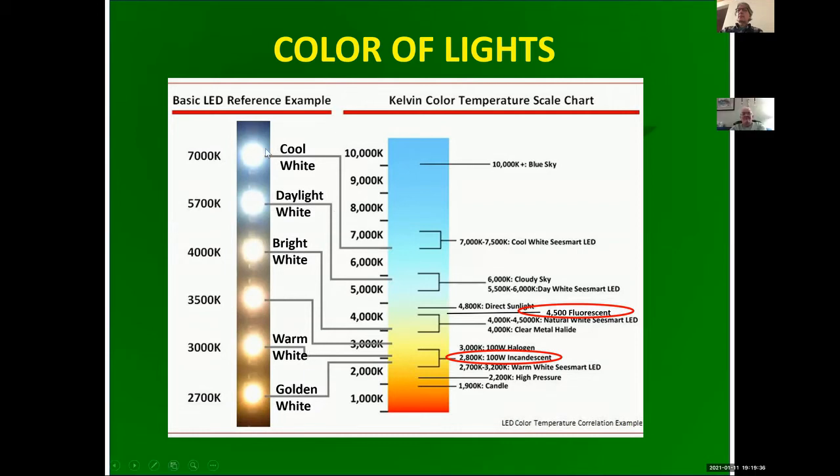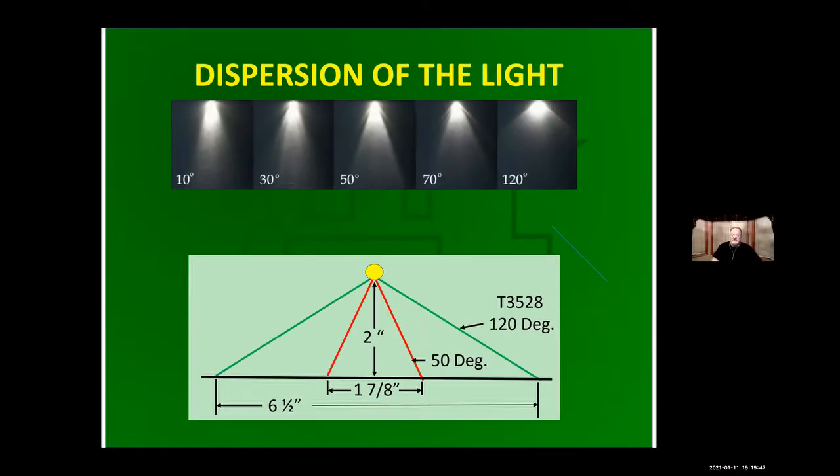I have not done that, but I'm going to do that shortly because I got some lights I think are too blue for me. Steve? Yeah, that's Tamiya. The Tamiya colors are translucent, and you can dip them in Tamiya and put an orange glow to a blue-white LED. Okay, Tamiya is the one. And you had good experience? Yeah, they work really well. You just want to control how much you dip in there. I dip them in, stick them in styrofoam, let them dry, then take a look at the brilliance. If I want to tone it down, I'll dip it again.